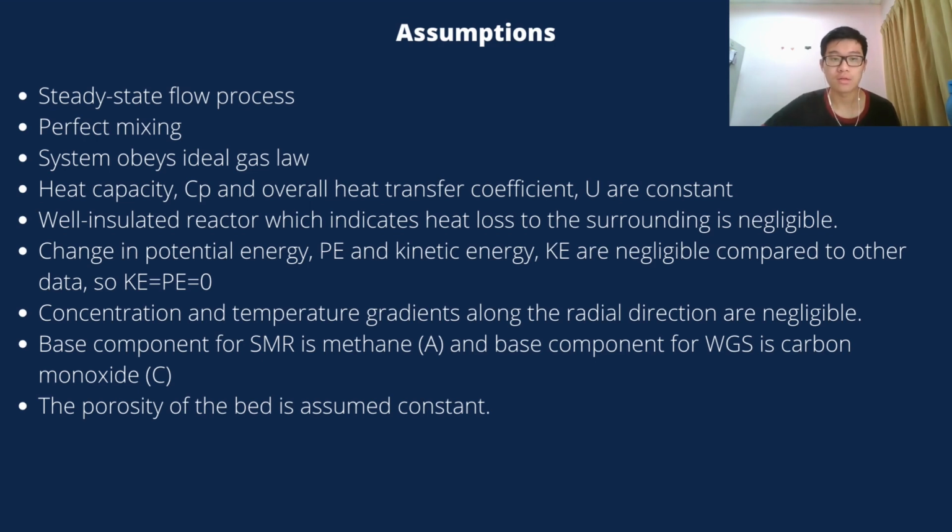Fifth, this is a well-insulated reactor in which heat loss to the surroundings is negligible. Sixth, change in potential energy and kinetic energy are negligible compared to other data. Seventh, concentration and temperature gradient along the radial direction are negligible. Eighth, base component for SMR is methane and base component for water gas shift is carbon monoxide. And the last is the porosity of the bed is assumed constant.